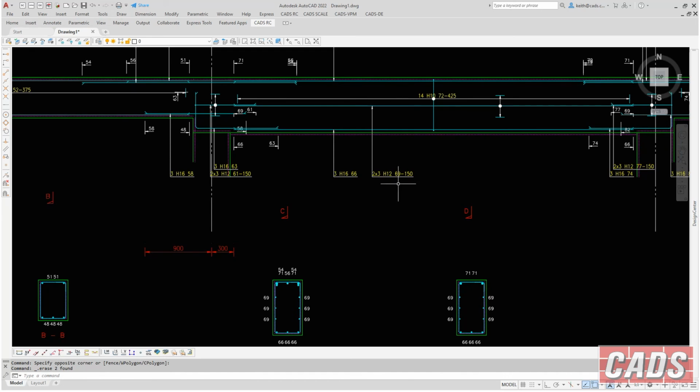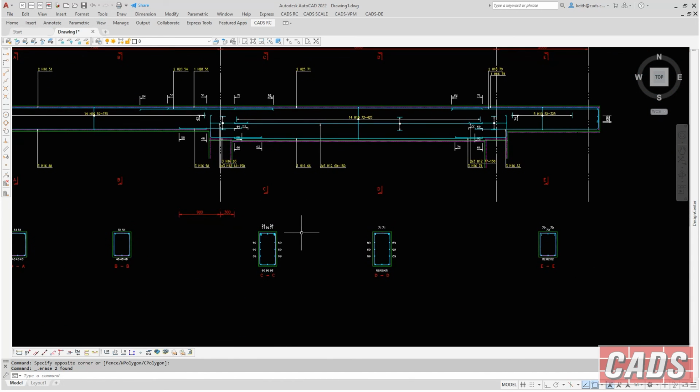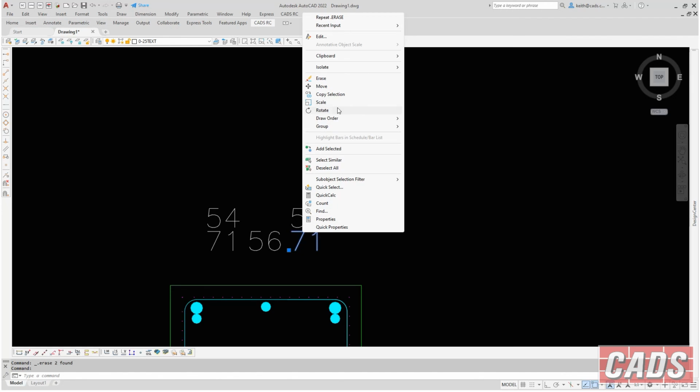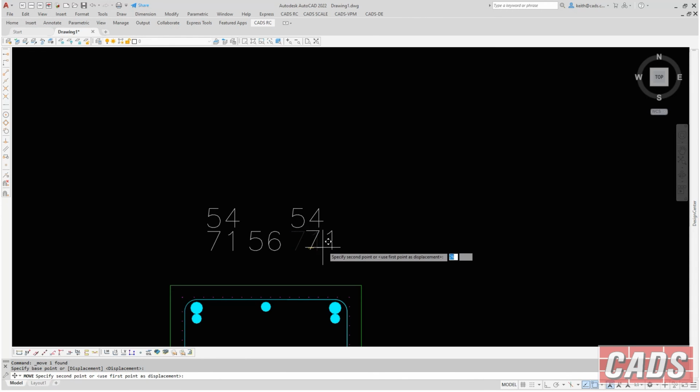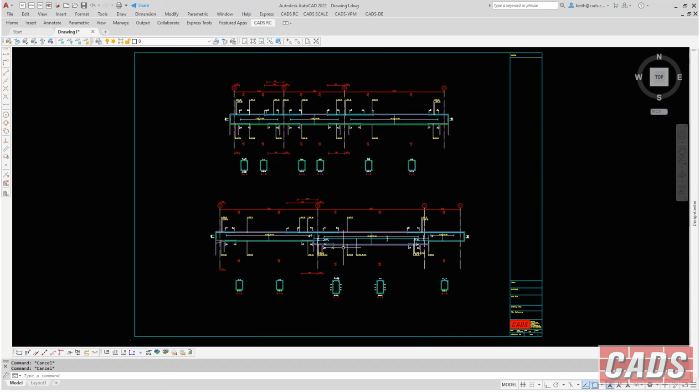You can see all the sidebars in there, the extra sidebars shown in the cross section. All the labels here, by the way, you can move these. They're not blocks or anything. You can pick a label here if you want to move it slightly. Not a problem. It's all very flexible, but gets you a great distance there in a very much quicker time.